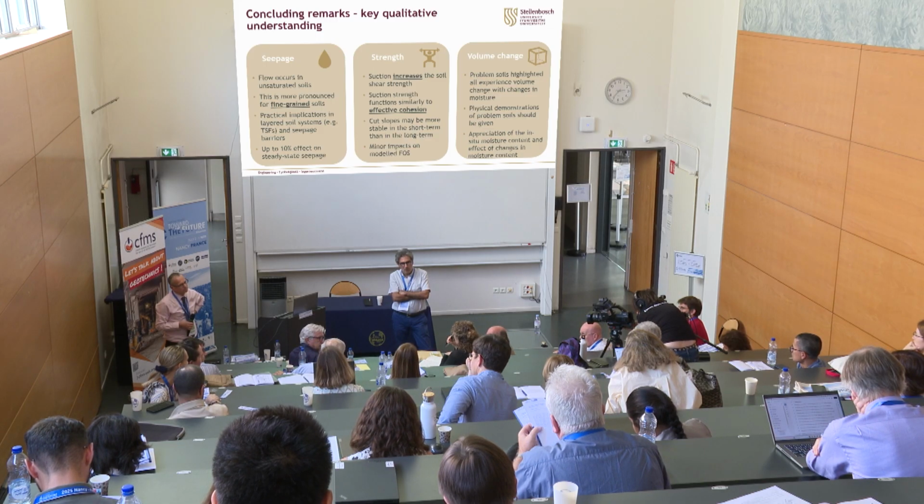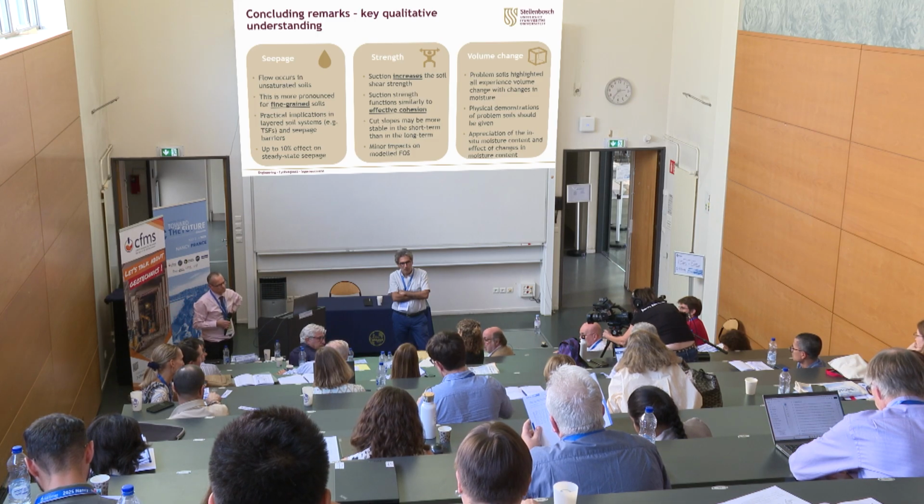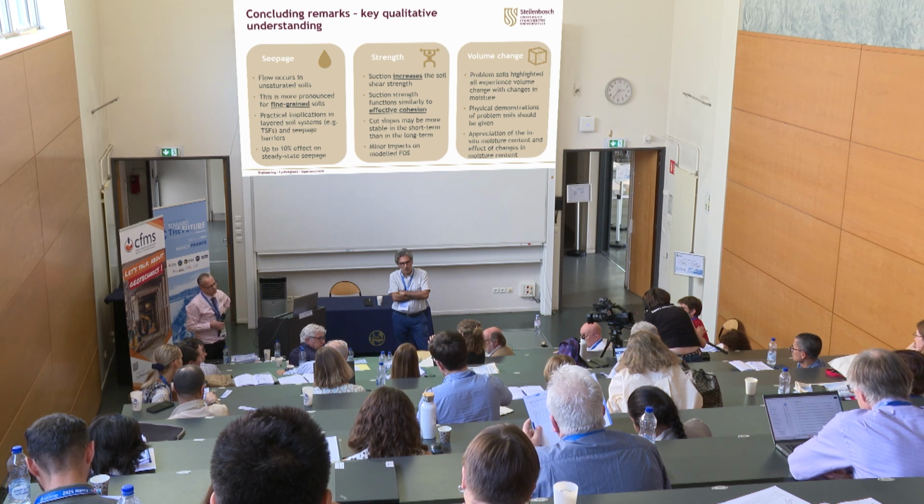And then, in my experience in my courses in the master, I introduced this explanation to jump from the Proctor plane to other variables that we use to model the initial conditions in practice. Because at the end, if they have to model a dam, for instance, they have to move from the initial conditions in practice with the dry density and the humidity to pre-consolidation to define the position of the LC and the suction with the water retention curve.